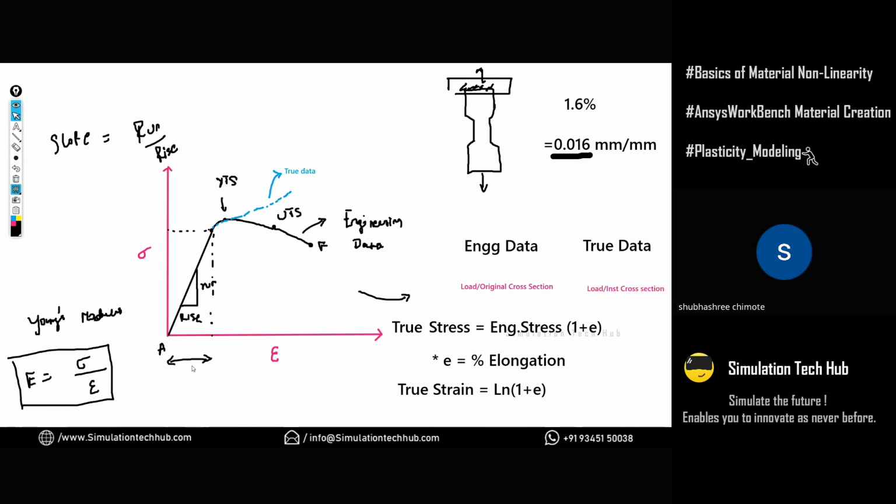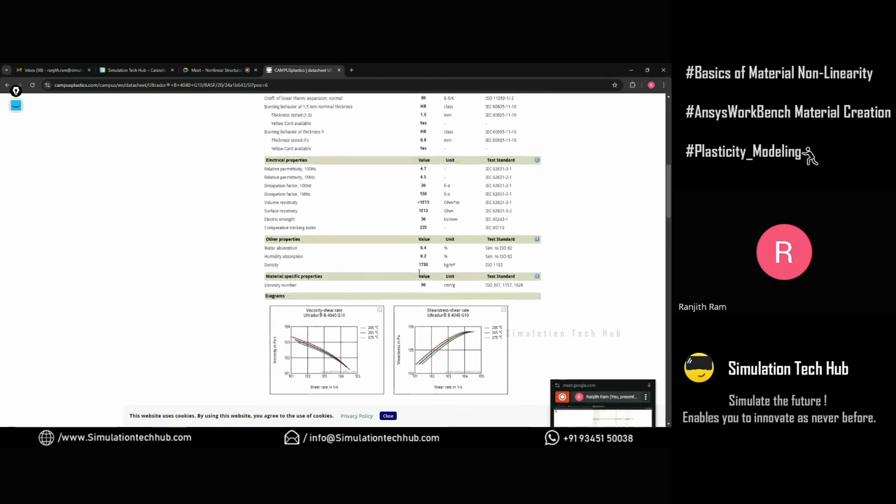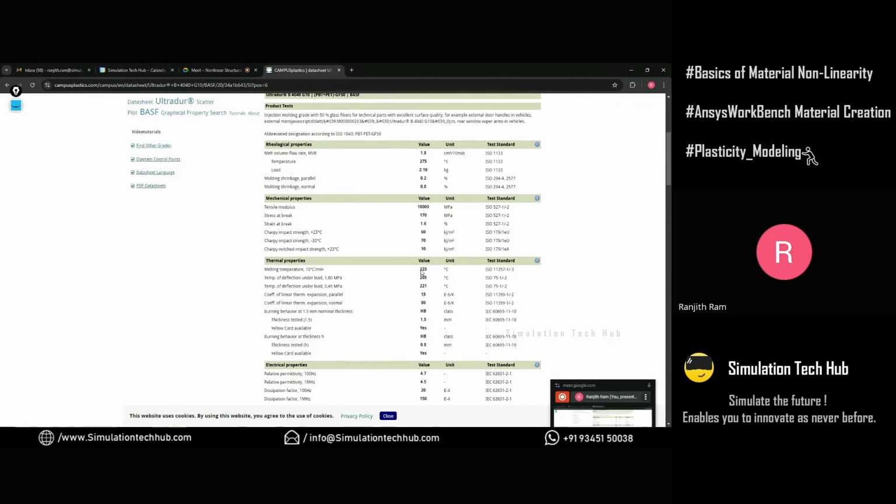This is the elastic limit, where it is starting. So at this point it is starting. After that, plastic deformation, plastic strain is there. Before that is the elastic limit. So this is elastic strain, epsilon E, and this is plastic strain, epsilon P. That's great. So the elastic strain could be the yield point, and you have to enter the yield stress at this location. Let's assume that on this material yield is something different, but from here itself we can see the yield point also. You'll go to the top and see the yield of the material.